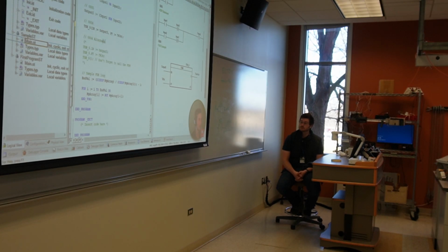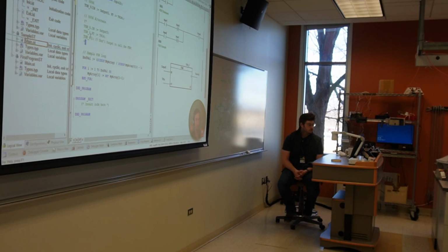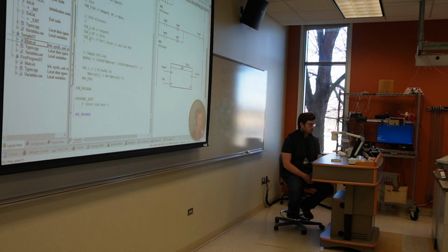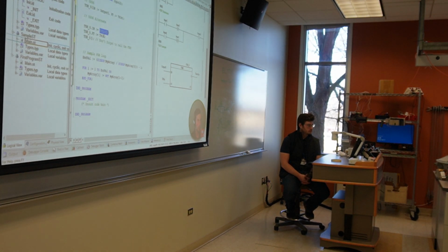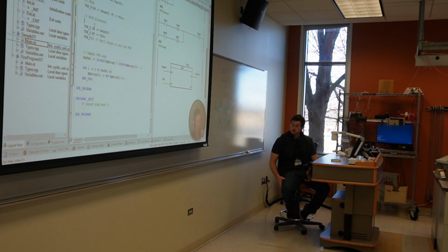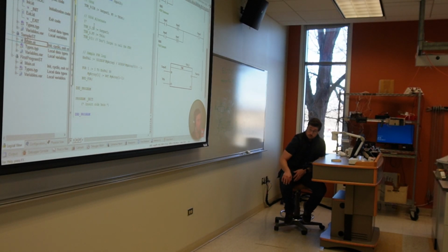All right, now let's look at the alternate way to do this. This is kind of the selectively calling things out. I'll uncomment it real quick so it's easier to see. In this case, we're actually calling out the inputs individually instead of all in one line. So you can see here, it's the exact same thing. I've got output 5, and then I've got my T hash 3 seconds for my elapsed time, and then I call my function block. Again, don't forget to call this, otherwise you'll be kind of banging your head against the keyboard trying to figure out why your code is not running. So that is the alternate function block call.